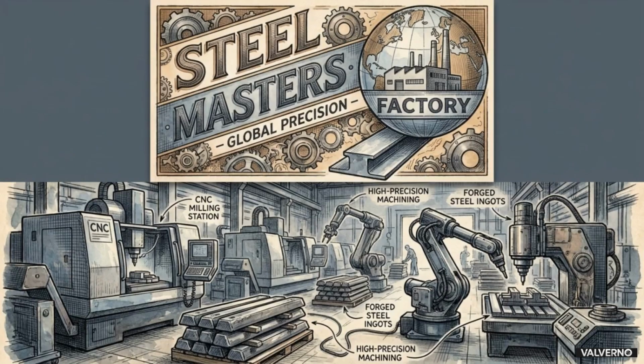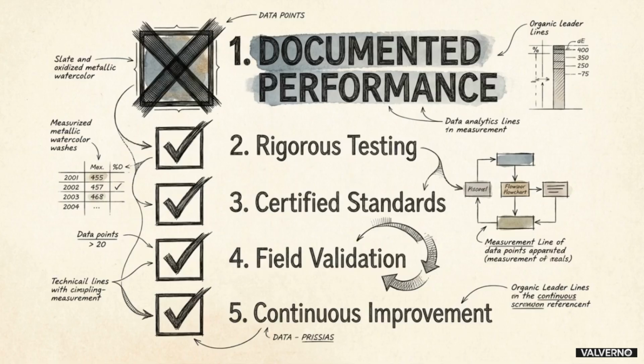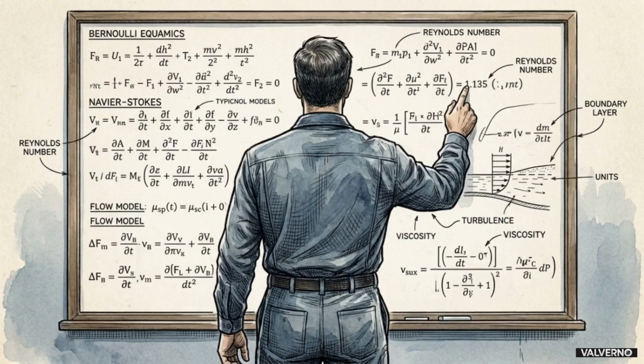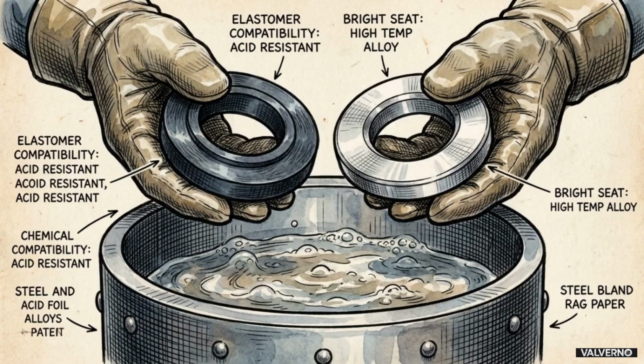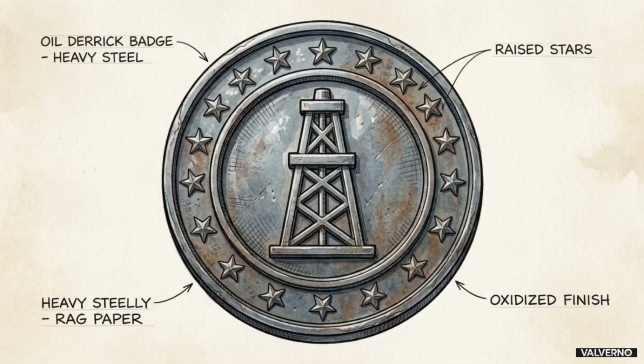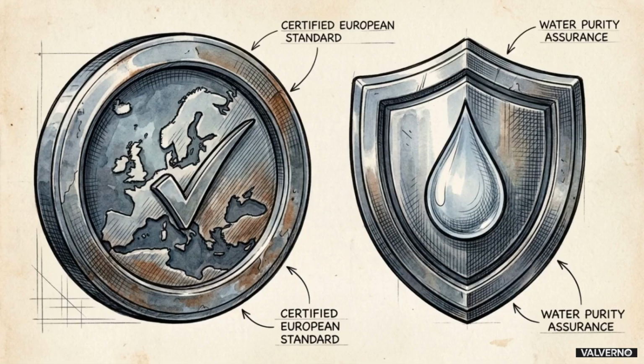Vetting a valve manufacturer in China requires looking past the marketing. Look at step 1 on this evaluation checklist. You must demand verified pressure and life cycle test reports. Confirming actual manufacturing capability means moving beyond basic price lists and requiring documented proof of performance. A high-value supplier acts as an engineering partner. They will confidently recommend specific seating materials based on your fluid media and provide accurate actuation torque data for your automated systems. From there, confirm compliance with API, CE, or RoHS certifications.